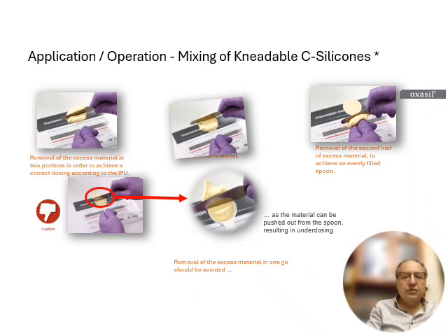For example, during the measurement of the putty with the scoop, it's better to take the spatula and take away what remains outside the spoon with two increments in two directions, because when it's folded, it might introduce error in the measurement.